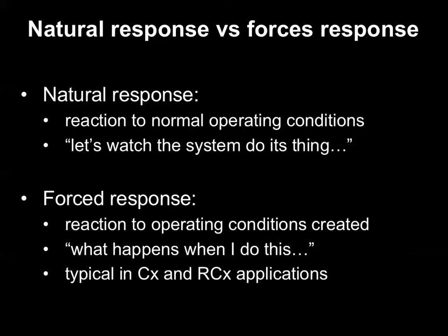There's two ways to do functional testing: natural or forced. Natural responses occur when watching the system react to change based on how it's been programmed or configured. So something like observing a normal startup sequence, or watching how economizer dampers modulate throughout the day. Forced responses are more common to RCX functional testing, since we're manipulating the system to have it show us what it does under some specific set of conditions. Examples of this include testing of system schedules, forcing a sequence through its reset range, sensor calibration checks, and equipment staging. But there's really an endless combination of system conditions that could be tested against.